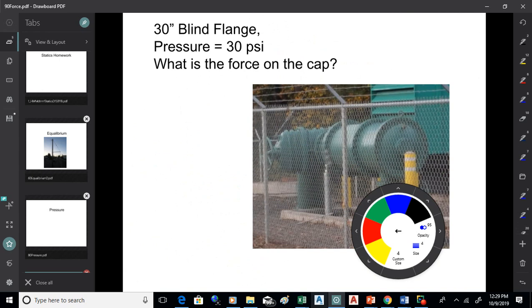It's a mess. There's also, you'll learn if you work for a city, a lot of places where you might have acidic soils, and they'll eat your services up pretty quick. There'll be some parts of the city where we replace them pretty quickly, others less so.